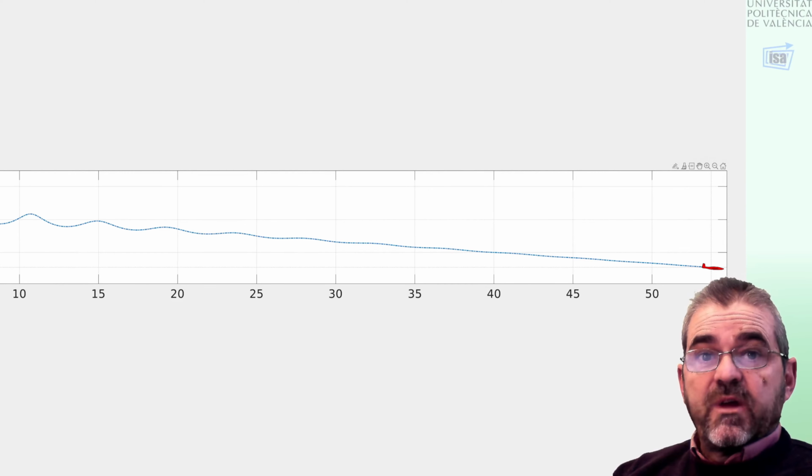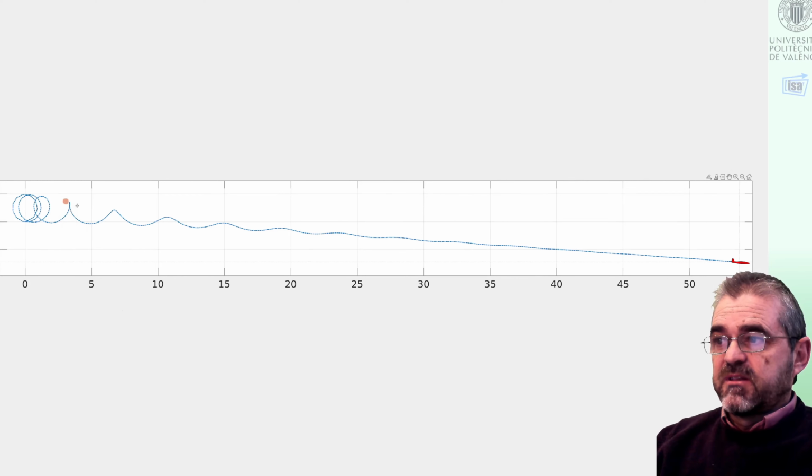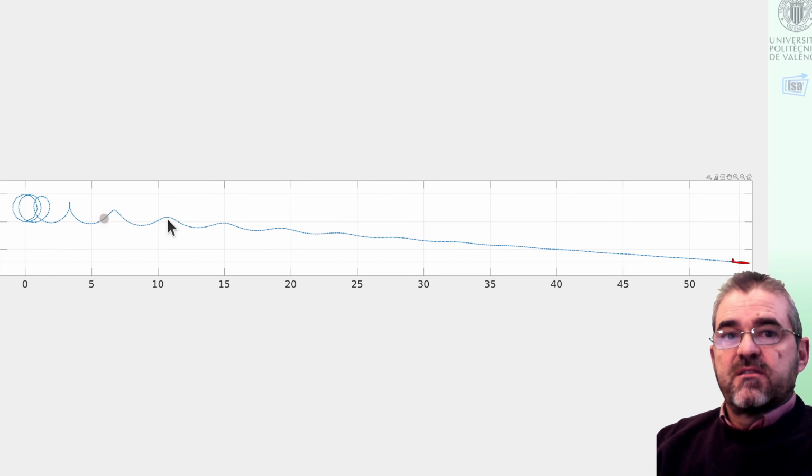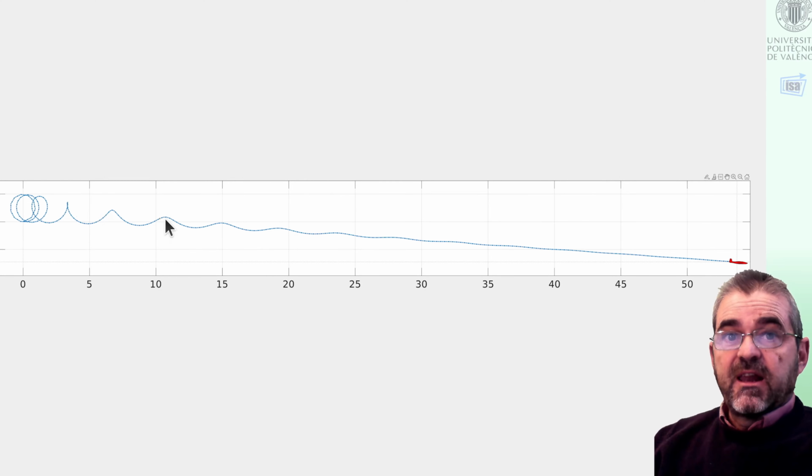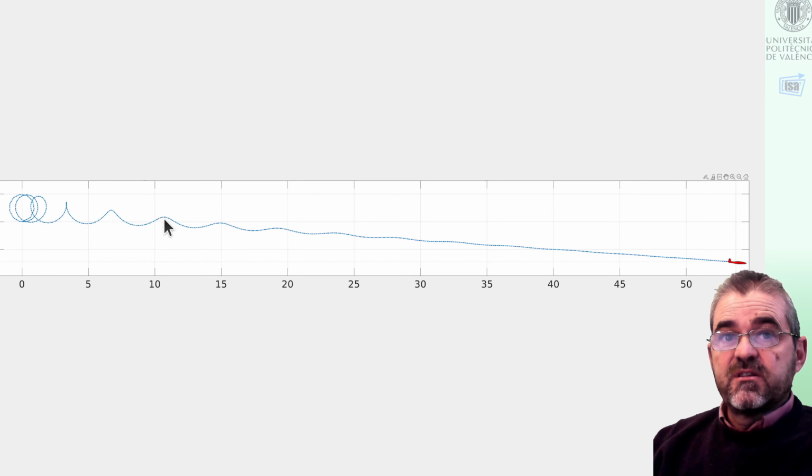And of course, when angular velocity is very high or linear speed is very low, particularly in here, maybe these simplified phugoid equations are not so reliable. But okay, the thing is that these equations approximately predict the looping behavior on a glider, because in here we are simulating zero thrust. Of course, in order to loop, we need a large initial speed. In here is just changing a line of code, but in real life, it may imply diving down from a high altitude.